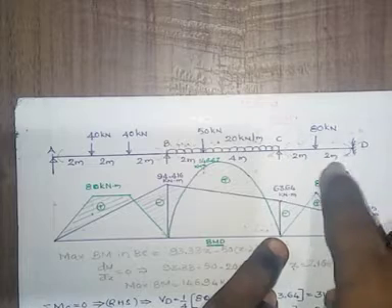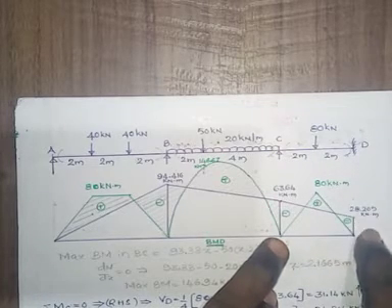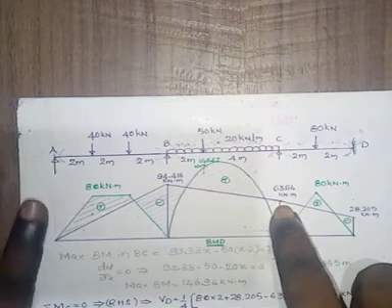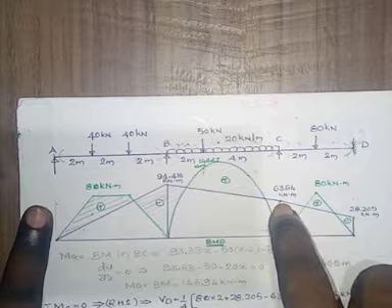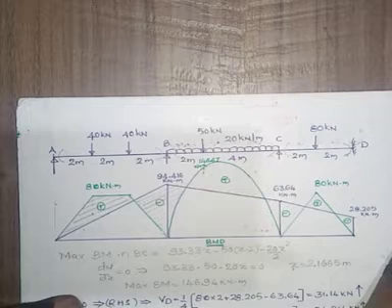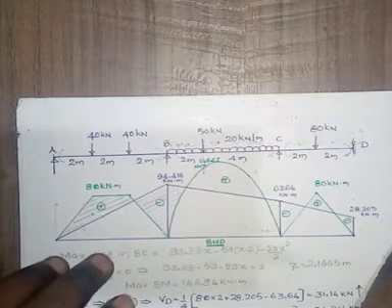Here, by observing, this one is again a hogging moment of 28.20. Draw an ordinate that is hogging, hence show it above the reference line and then join this. Here this is the support moment diagram. Now we want to draw the simply supported beam bending moment diagram.